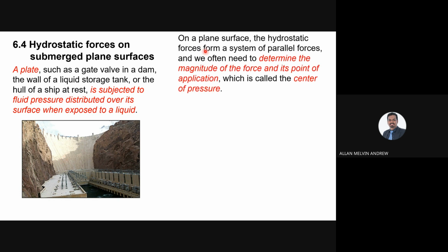Okay, on a plane surface, hydrostatic forces form a system of parallel forces, and we often need to determine the magnitude of the force and its point of application, which is called the center of pressure. Usually in the calculations, engineers will check how much force, the magnitude, meaning the amount of force the surface will be subjected to. In those times they did the calculation manually, but now it is mostly computerized.